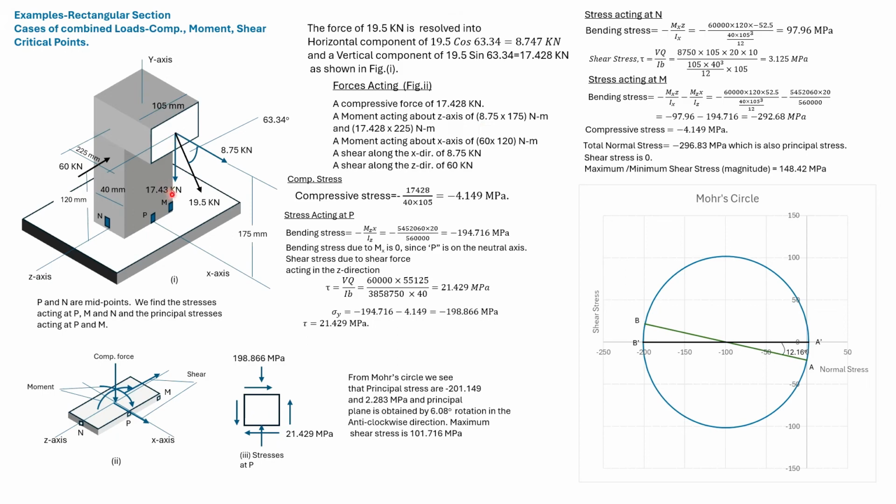The vertical force causes a compressive force and also a moment about the z direction. This force causes a shear along the z direction and a moment about the x-axis.